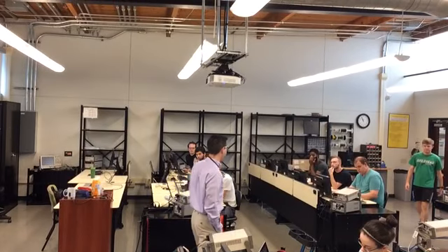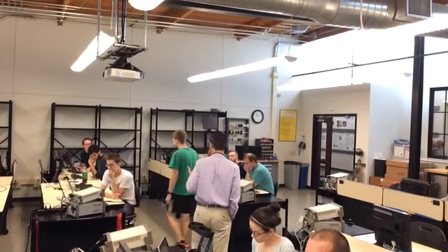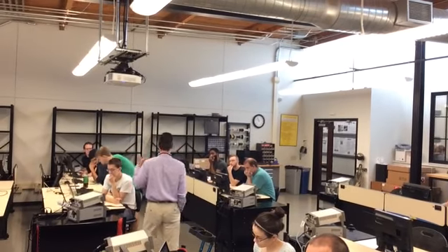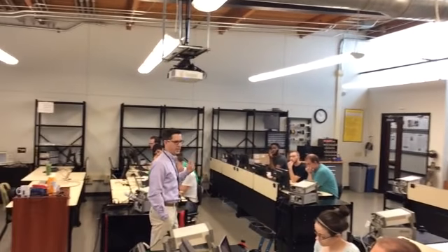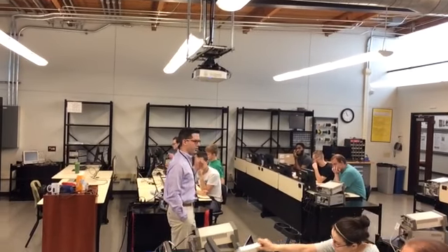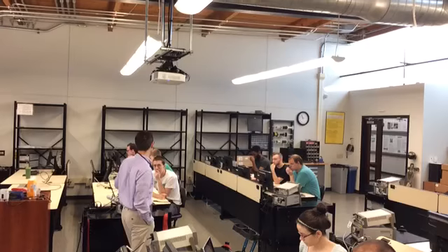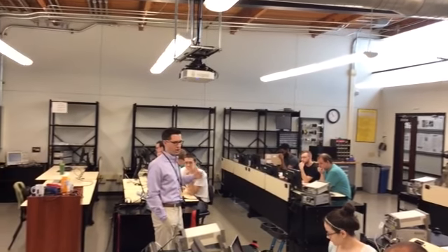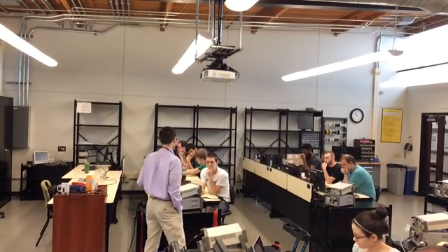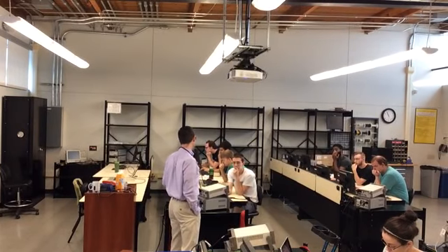One thing about Lab 1: the buttons are called PB0 and PB1. That does not mean that the buttons live at port B0 and port B1. It's a terrible way that the user manual calls it, but that does not denote the location of the button inside the processor. You're going to have to use the user manual and manually look it up.